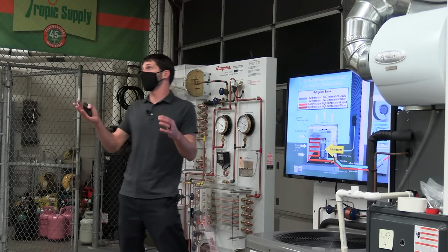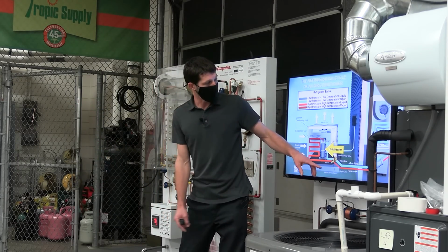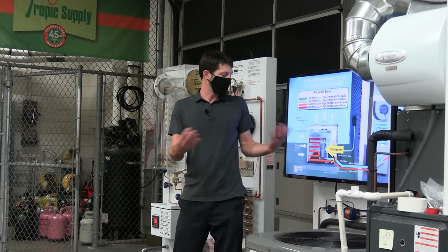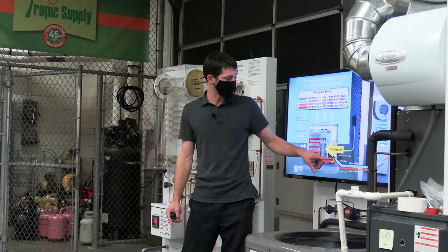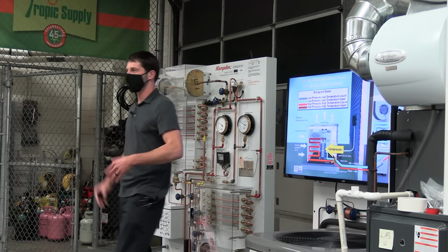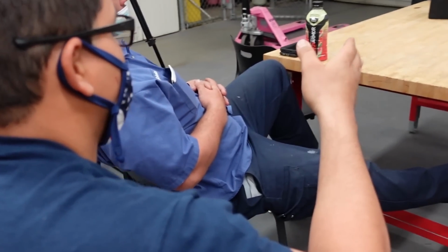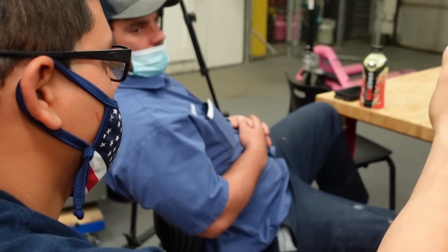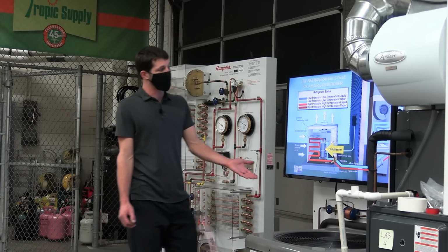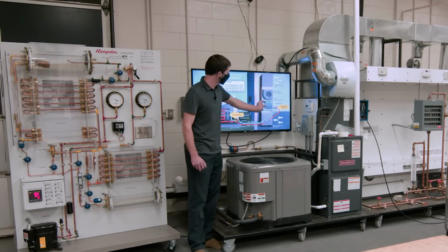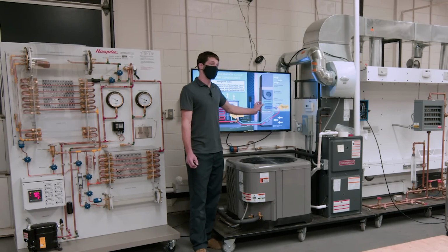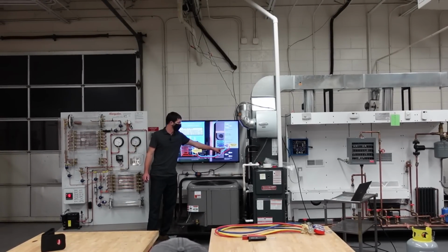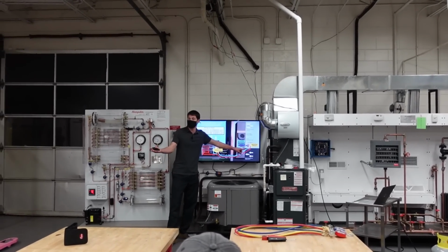Too high of a superheat, and what's going to happen is that's when it comes out right out here, and you're going to notice even, say, this at the service valve, maybe it's not even sweating, and all that type of stuff. Yes? That also means that the evaporator coil is going to be hotter or not 40 degrees? Yeah, it'll be a higher temperature. The saturated temperature may be higher, but really what it comes down to is the vapor temperature exiting this coil is going to be a lot higher than what it could be if it was more efficient.